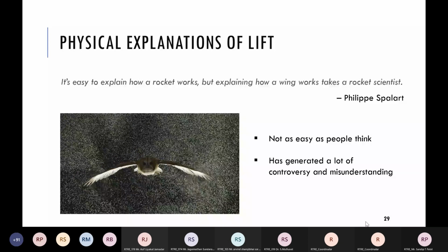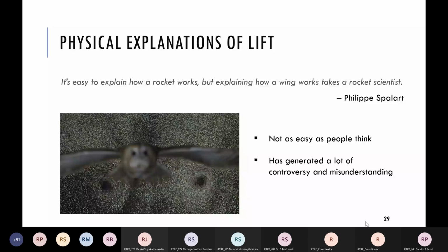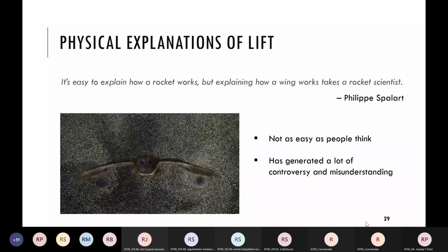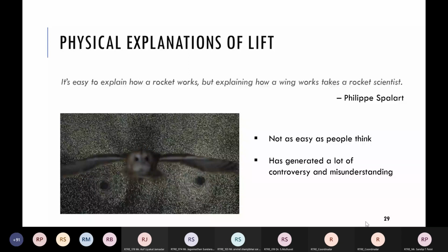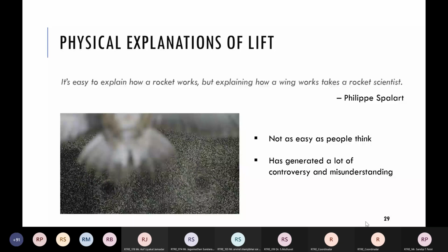In schooling, in order to simplify things, there is one explanation in which it is given that the fluid particle moving on the upper edge of an airfoil moves faster in order to reach the tail, while at the lower edge the particle moves slower, so that both particles start at the same time from the nose and reach the tail at the same time. That is a completely wrong thing.